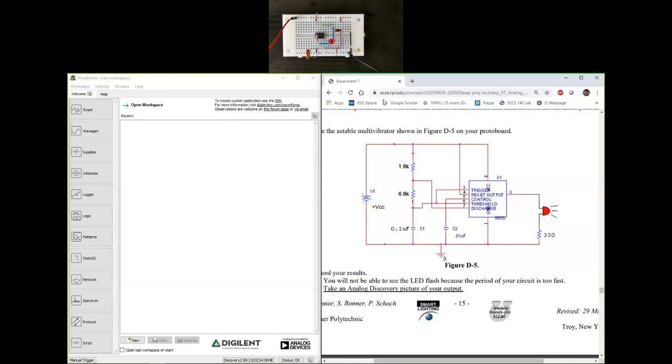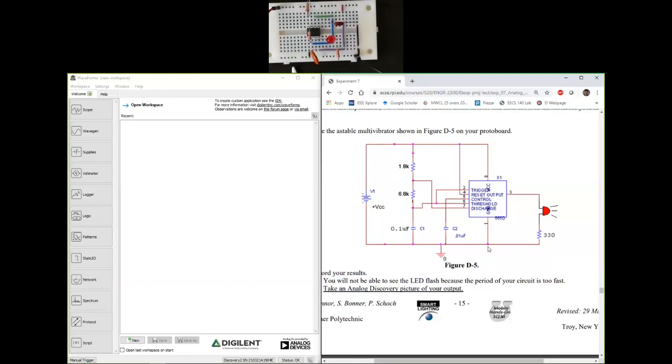Next, the simple connections first. That's always my process. So pin number 1 goes to ground. That's the chip right in the middle, and you have a notch there on the left side. So that means the leftmost pin on the bottom is pin number 1, through 4, then 5 through 8. If I look at pin number 1, that's connected to ground, and if I move this capacitor out of the way here, pin number 1 is connected to ground using that black wire there.